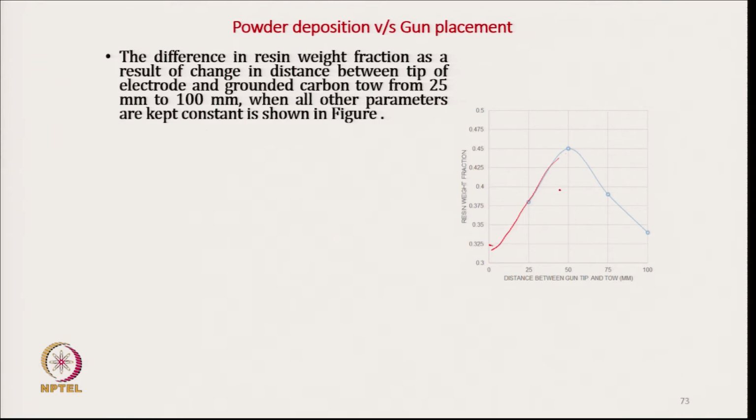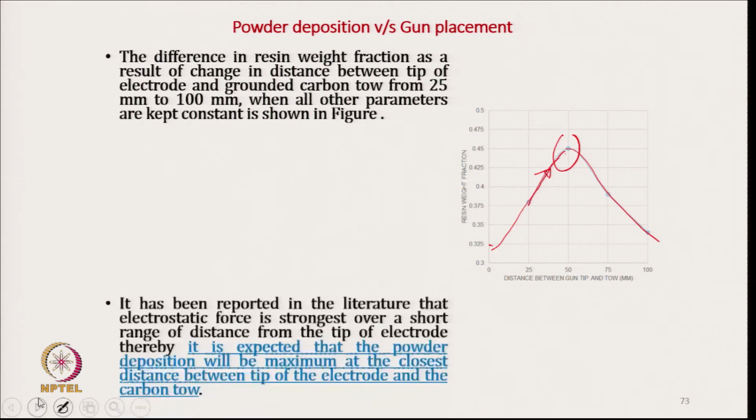and with the increase in distance, deposition increases up to say 50 millimeter, and beyond that if we further increase the distance, the resin deposition drops drastically. So, from 25 to 100 we have observed here.